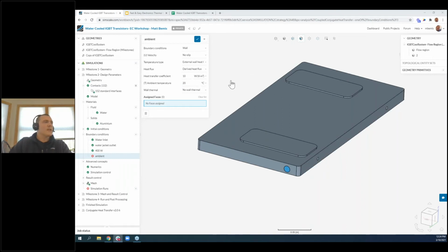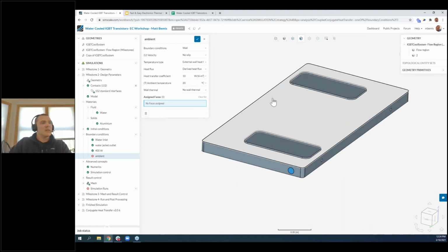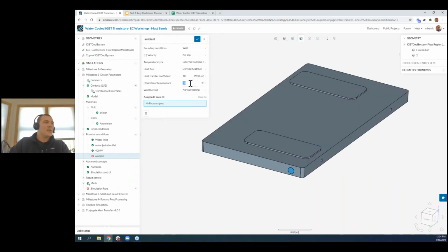What we're saying here is, let's assume the top face is 1 meter square. And let's assume I said ambient is 10 degrees, maybe it's a cold operating condition, and the plate happens to be 20. Well, we have a 10-degree delta, we have a 1 meter square, so there's going to be 100 watts being discharged. So 10 times 10, there's going to be 100 watts discharging to the system.